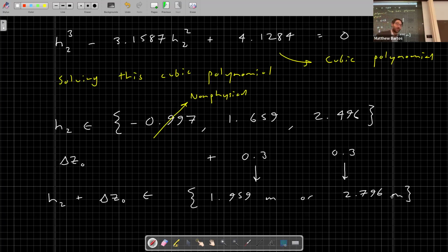Very good. So you may remember from fluid mechanics, subcritical and supercritical flow. So the flow can be traveling at either one of these conditions. It turns out that this answer here corresponds to subcritical flow. And this answer here turns out to correspond to supercritical flow.